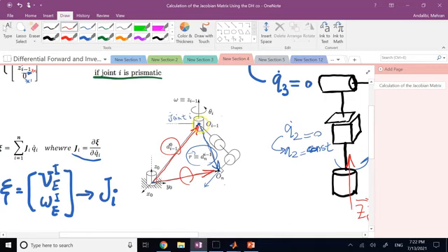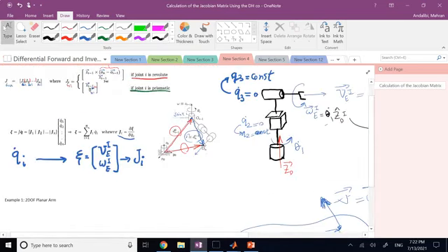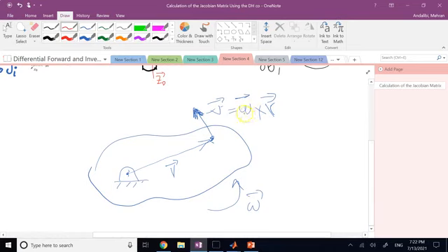This is the origin of frame i in base. This is the origin of the end effector in base. If I subtract, that's r, and that's exactly what you see here. This is that r vector. Okay, that you're seeing over there. Now, why is it cross multiplied by z_{i-1}? Well, because this omega that you have has theta i dot in it. That's the magnitude of the rotation.